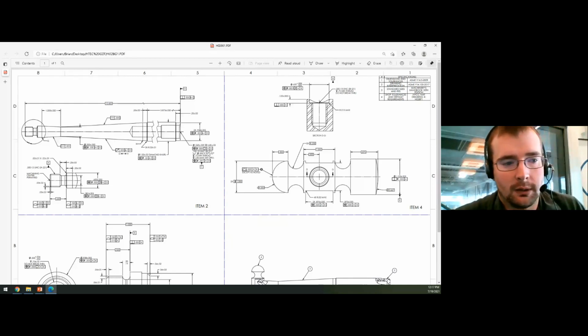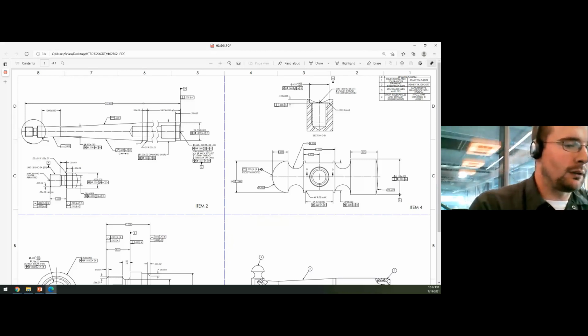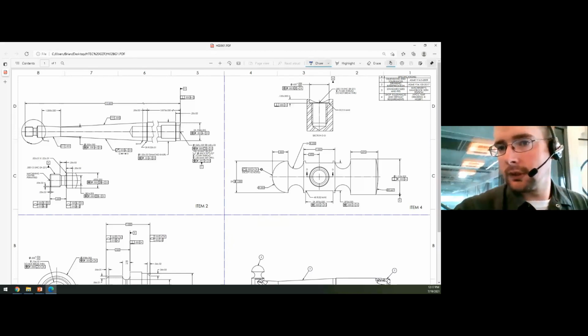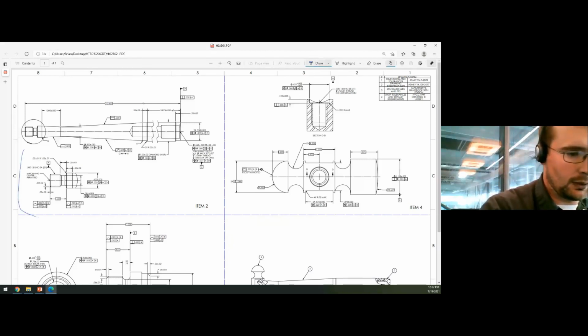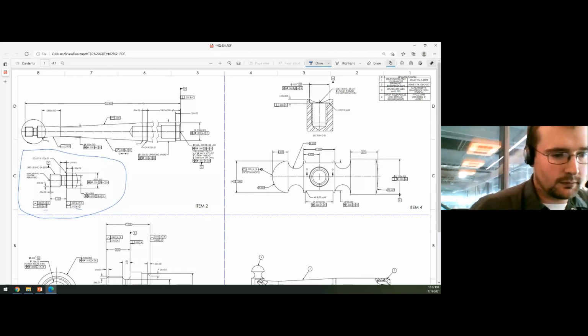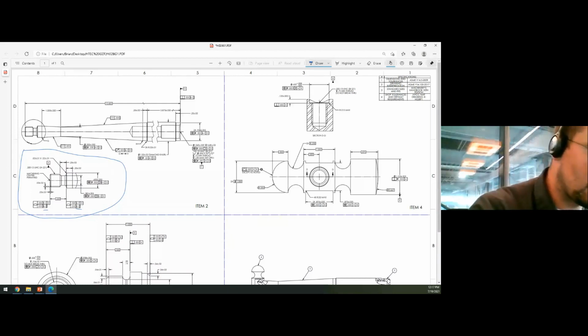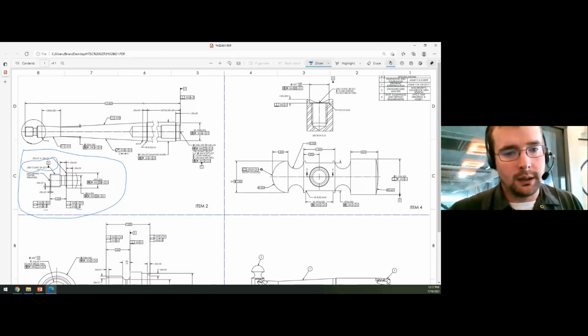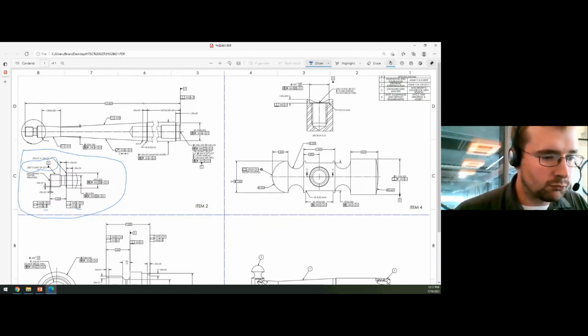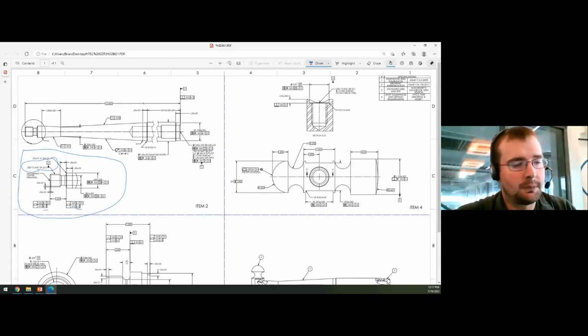You have the different alignments on this over on the hammer handle here. And you have the A-C alignments, and the composite control for profile of a surface and what that means and how to control it, and the thread specs. That has really helped us, because the big thing with a lot of the students, they say, well, what matters to what, and how does it measure to? And that really covers the datum system very well.